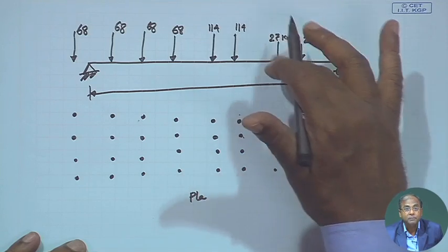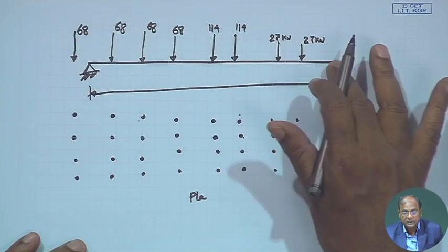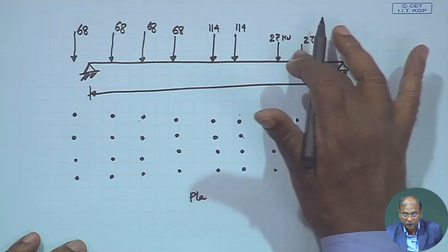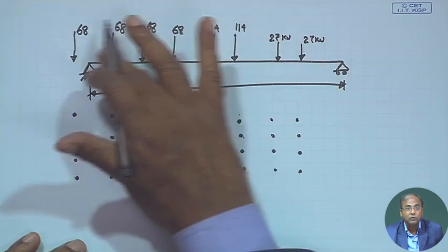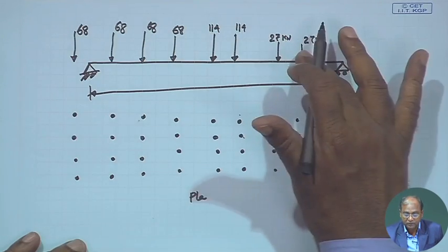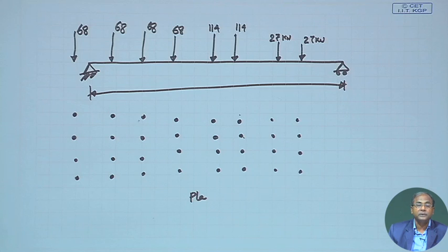that one will be replaced along the girder. If I consider that is a simply supported beam, along the girder I shall get the new value of that, we shall find out, and on the basis of that we have to find out the bending moment and shear force, and when we get that, then we can solve that, we can design it. So, our objective is that we shall find out the bending moment and shear force.